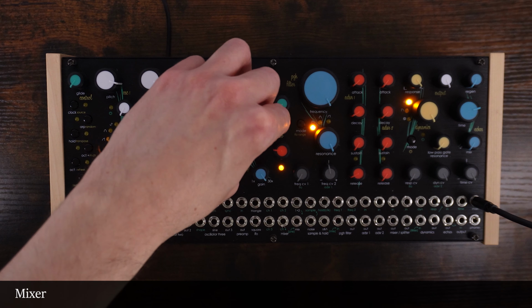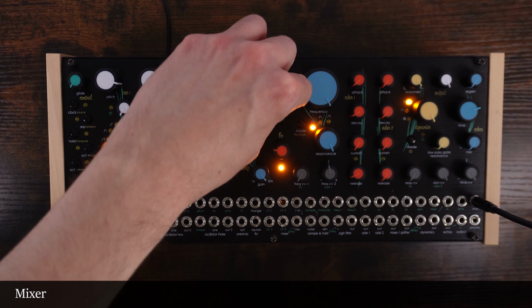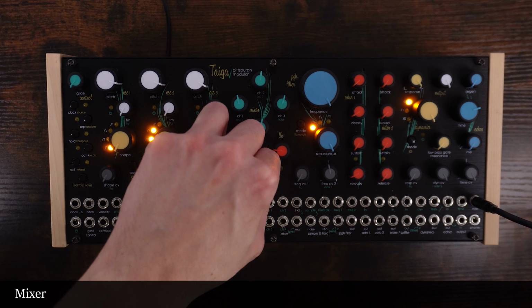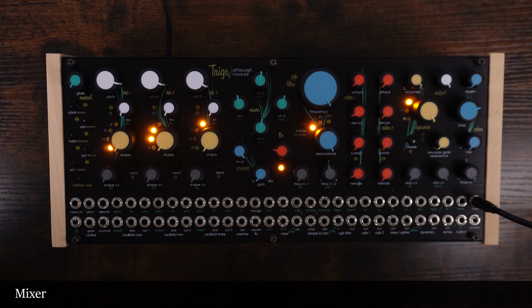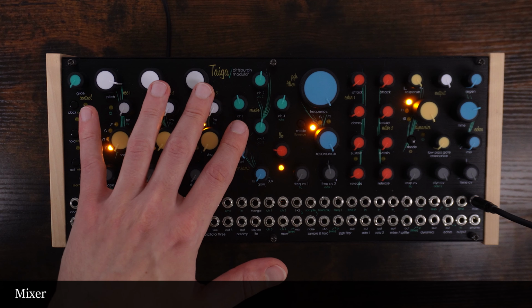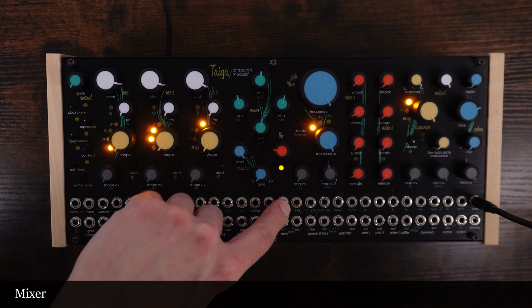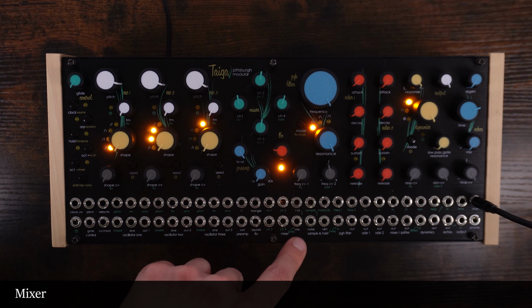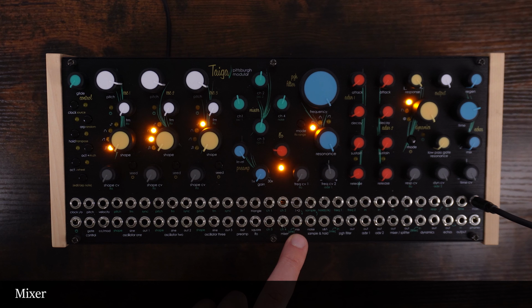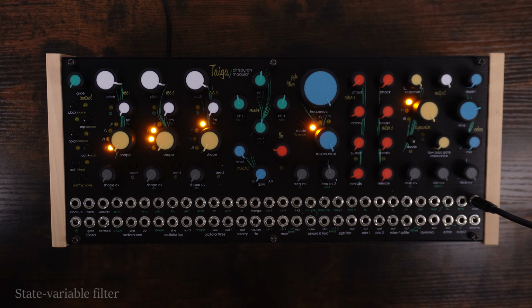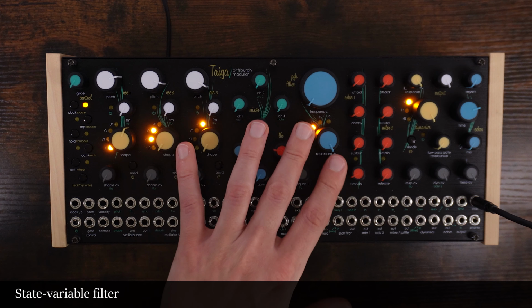The output of the 3 oscillators and the noise source, as well as the input of the preamp, are mixed in the mixer section. The preamp can amplify any signal up to 30 times, which makes it usable to bring up line levels to Eurorack levels. The mixer acts as a 5-channel mixer by default, but you also have the option to take out the signal from channel 1 and 2 separately to channel 3 to 5. The mixer accepts CV and audio, so you can also mix your CV signals, but there's no CV control over the mix. The summed output of the mixer is routed into the filter.